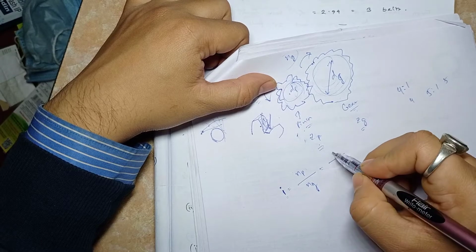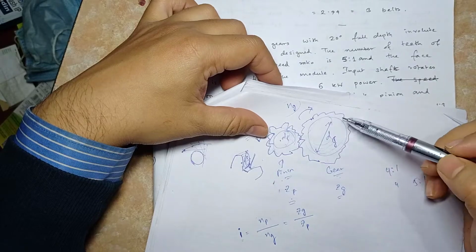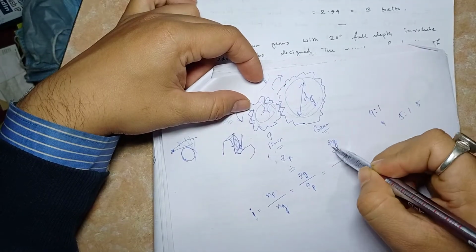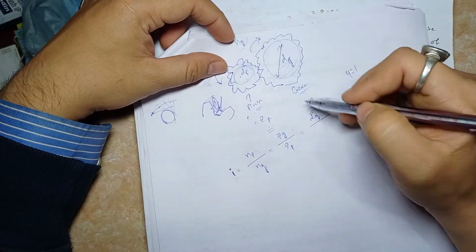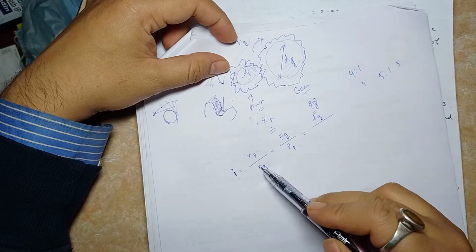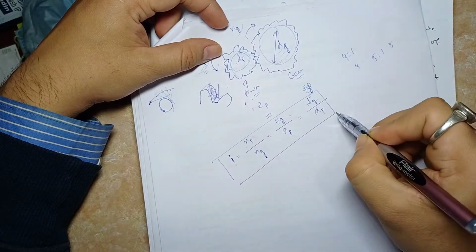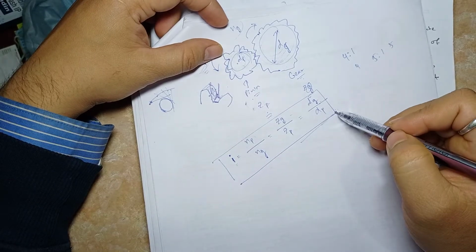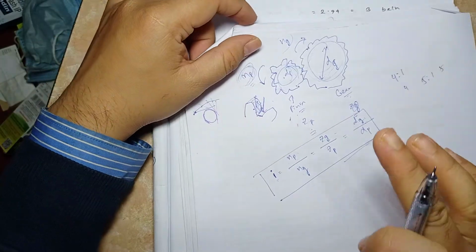This is equal to the inverse of the gear teeth ratio, because the larger one will have slower speed. The larger one also has a bigger diameter, so the number of teeth is also more, but its speed is less; that's why it is inversely proportional to speed. So np by ng equals zg by zp equals dg by dp. This relation is called your speed ratio. It is a useful relation, so using it you can find out number of teeth, diameter, and speed. Now you have understood this.